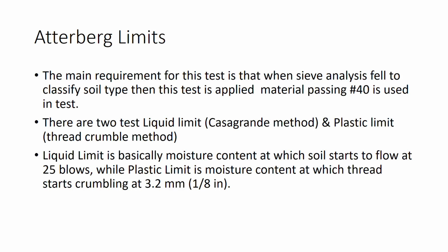It is basically related to the Atterberg limits. In Atterberg limits we have the liquid limit by the Casagrande method and the plastic limit by the thread crumble method. The material required for these two tests should be passing the number 40 sieve.